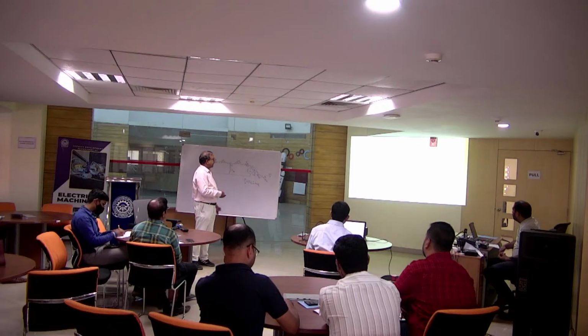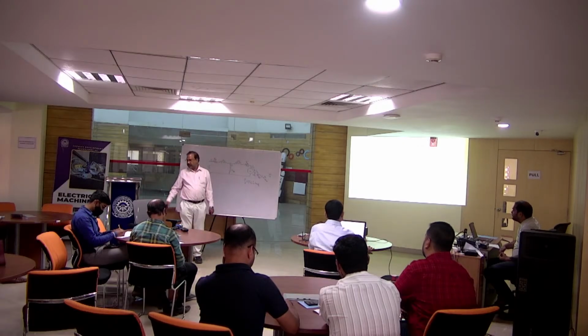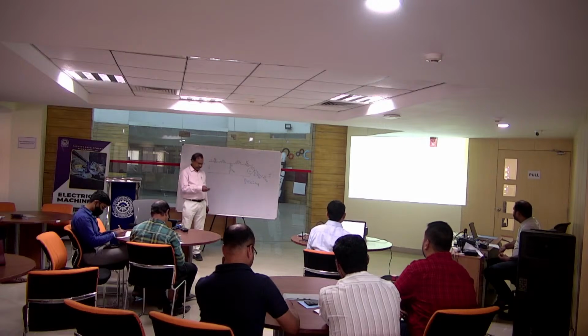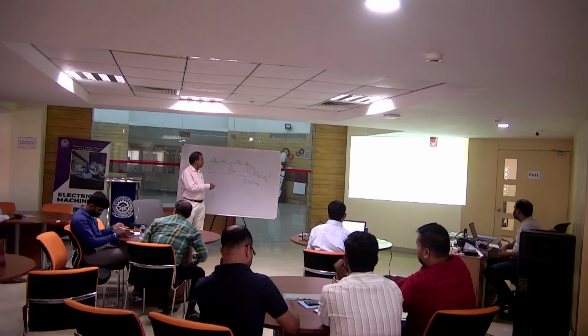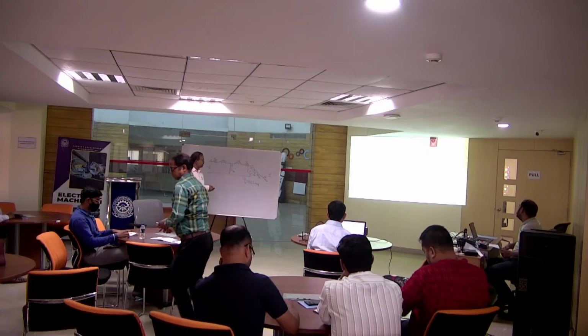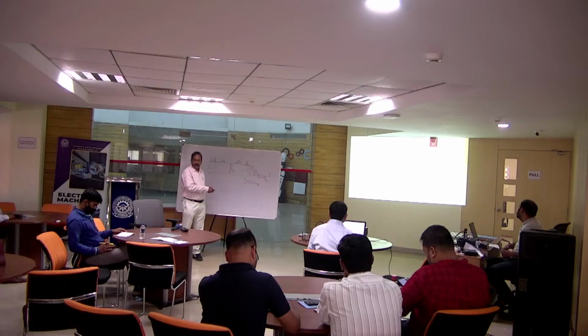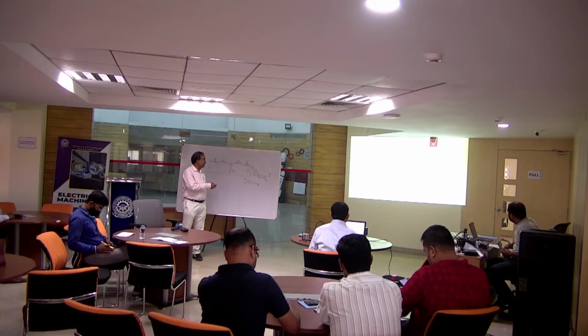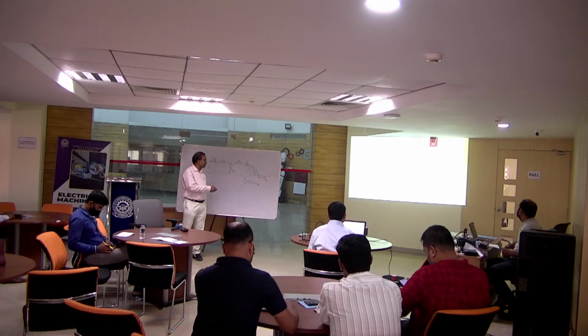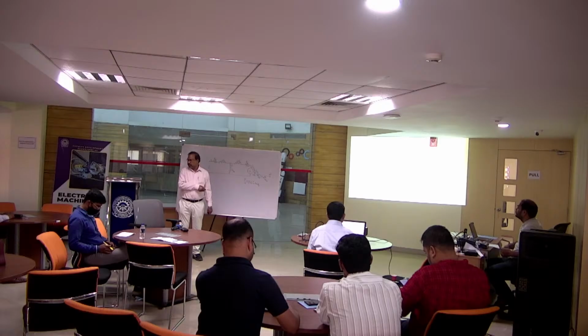This is a static system, another scheme, which I was also going to explain. This is the second scheme. Here again, this is the original slip ring induction motor supplied from the three-phase mains. The rotor terminals give slip frequency AC, converted from AC to DC by a diode rectifier. This is the DC link. Then there is a three-phase inverter, whose AC terminals are connected to the three-phase mains through a transformer.